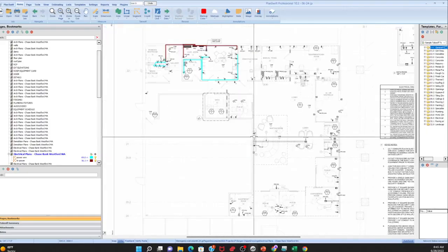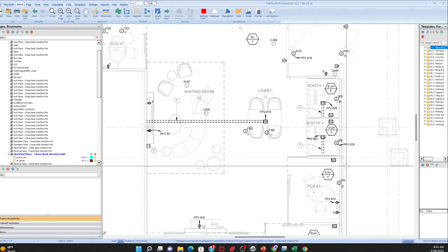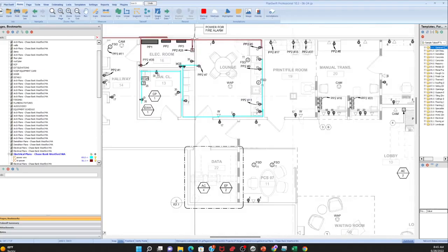There's multiple ways. Just know that the regular outlets are all number 12s. And for the daisy chains, you have to ask in your state, but it's usually MC cable. It could be MC cable with 3 wires, 2 wires, 4 wires, and we usually just use 3-wire MC cable, the same as the home.